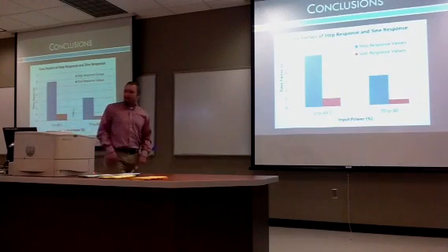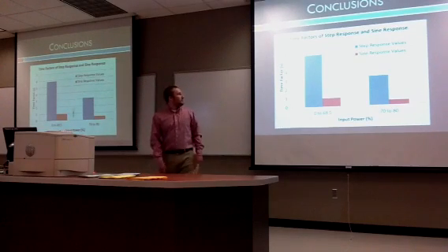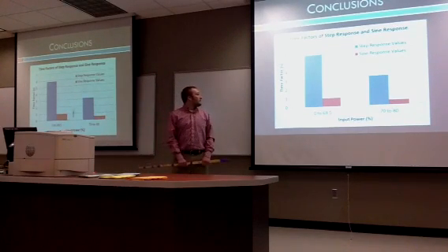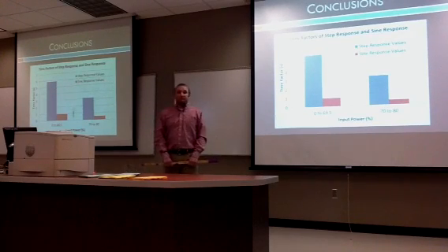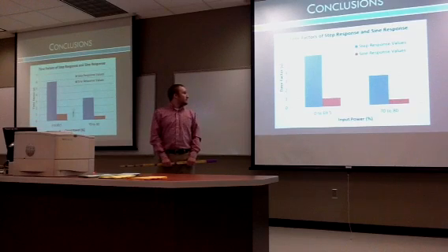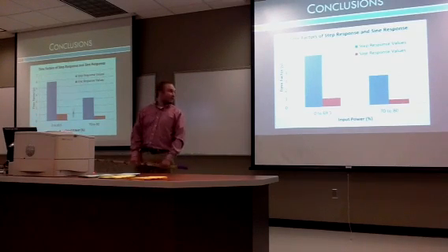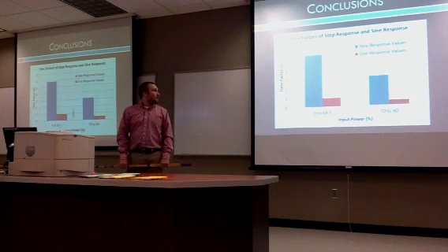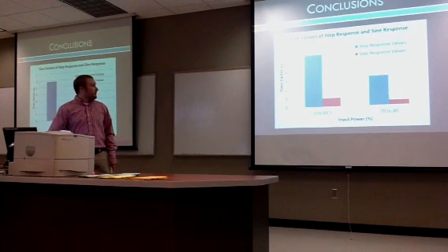And our time factors for the step response and sine response, again, it was a dramatic difference. For 0 to 69.5% input power, the time factor went from about 5.8 seconds down to about 0.9 seconds. And for an input power of 70 to 80%, the step response value time factor was about 3.1 seconds, and the sine response value for the time factor was about 0.5 seconds.